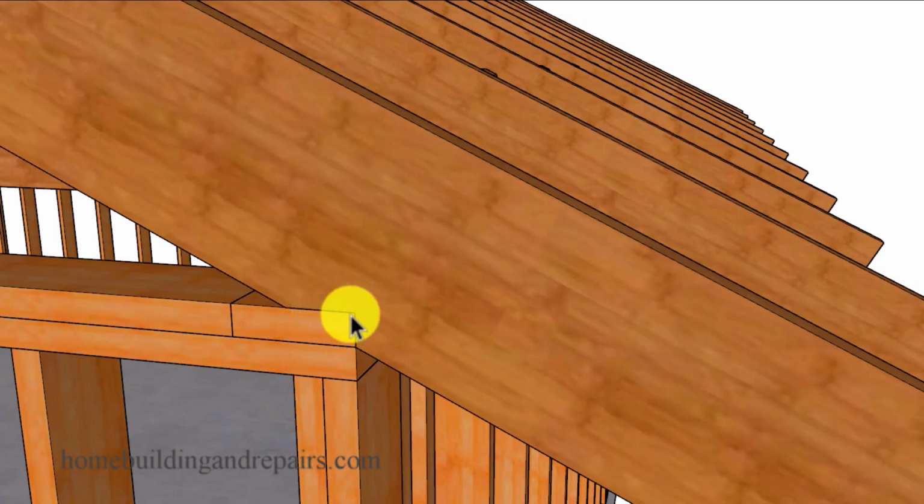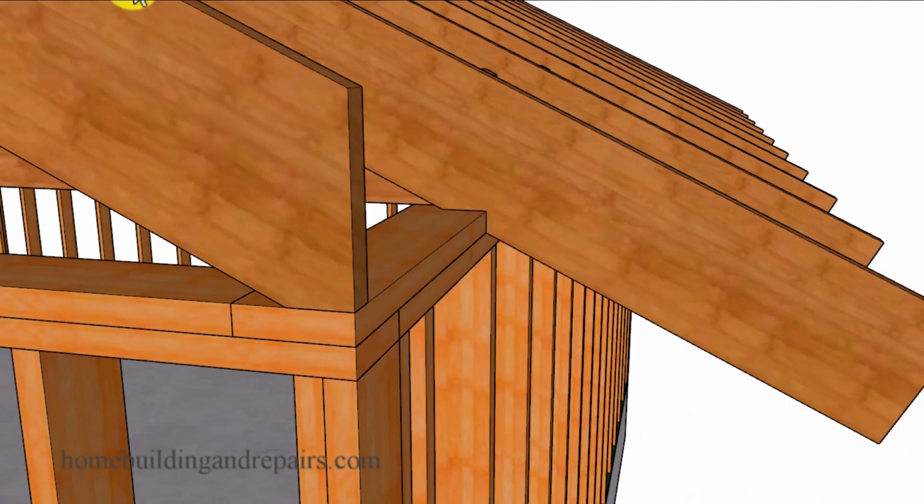And you can kind of get an idea by watching the rest of the video that one of the sizes will dictate the size of the other size. For example, if I make this one longer, then this one here is going to be longer. And if I make this one here shorter, this one here is going to be shorter. And I'm not about to suggest that's going to happen all the time, but the main part I'm going to focus on in this video, the most important one to me, is going to be this cut here, or the level cut. And I would like to see this at least 2 inches long.